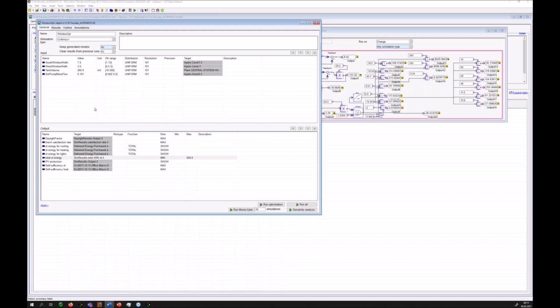So as you know, we can do different parameter runs with the same setup. We have the Monte Carlo and we have this optimization run where we have the Automo option here. Monte Carlo simulations have the advantage that all 120 cases can be simulated in parallel when working on the cloud, while Automo will only run a limited number of cases in parallel and then use the experience from those to decide about the parameter input sets for the next generation of cases. This will cost more waiting time, but it will save total CPU time, and that is what costs, or what will cost you.